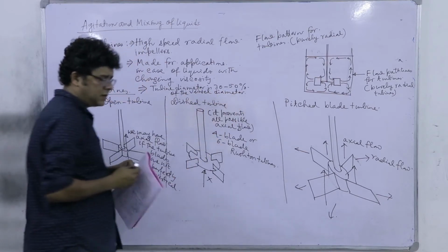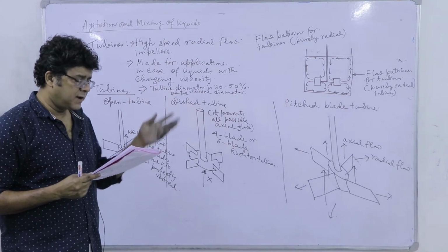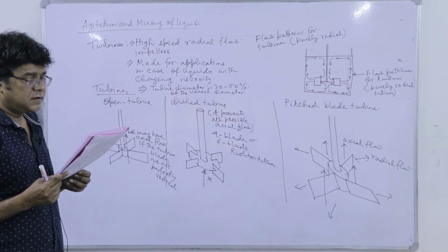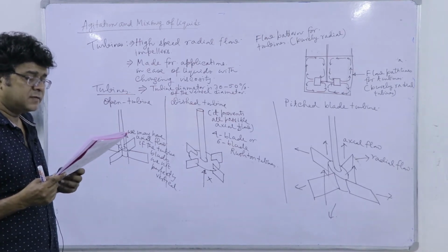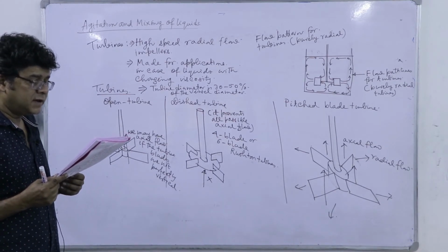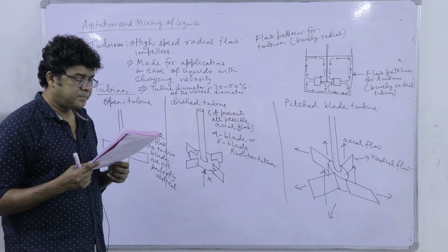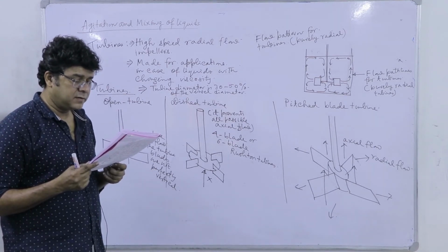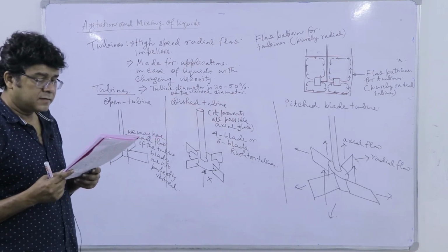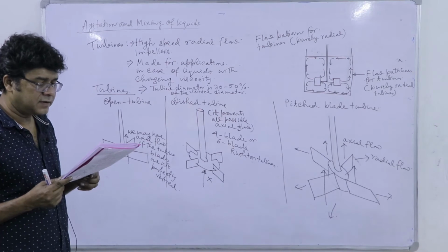So, anything which I have missed, let me check. Here it is effective for a very wide range of viscosity. I have told that in low viscosity liquid, turbines generate strong currents that persist throughout the vessel, seeking out and destroying stagnant pockets. It is obvious. Near the impeller, a zone of rapid current, high turbulence and intense shear is generated. The principal currents are radial and tangential. The tangential currents induce mixing and swirling, where tangential means in this direction, in the circulatory direction, the azimuthal direction.